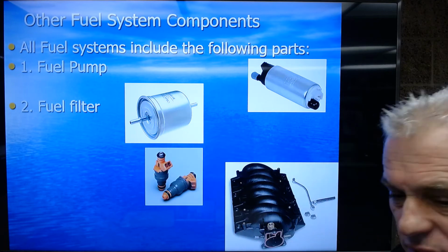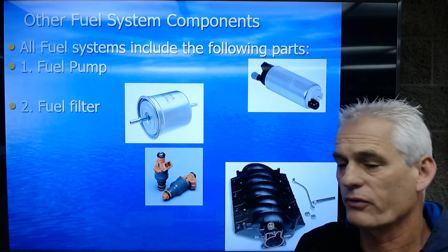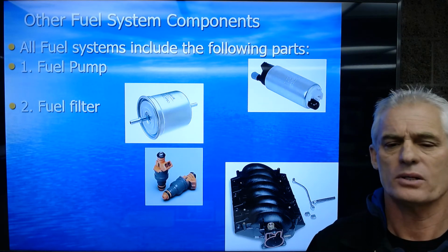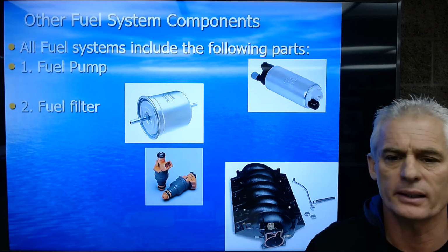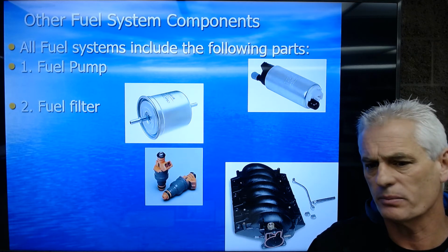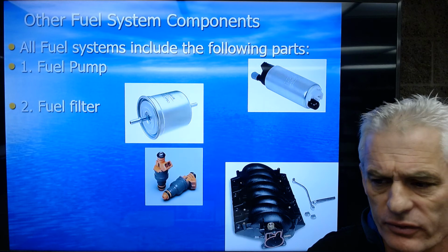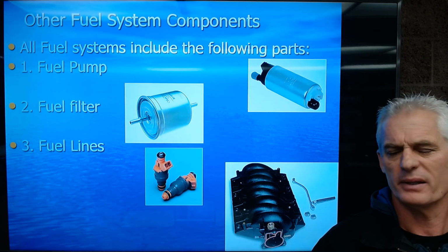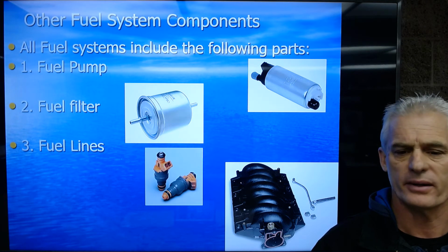Since the early new millennium, in California in particular, and I think probably federally, we have stopped putting filters outside of the gas tank. So all of our filters are in the gas tank now, and they're not usually easily serviceable. But I have always recommended replacing fuel filters every year at 15,000 miles. The industry's usually accepted interval is every 30,000 miles.